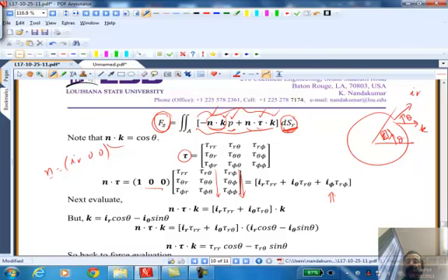Now this, of course, will be 0. Why will that be 0? Because of axisymmetry, right? So this will involve, for example, derivative of v phi with respect to r, which is 0, or Vr with respect to phi, which is also 0. Okay, so this will be 0 because of axisymmetry. So there are only 2 terms that are non-zero.